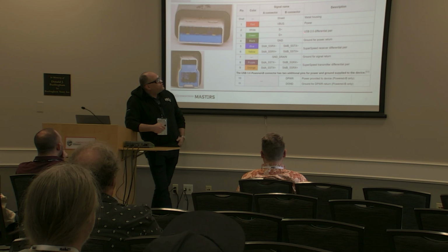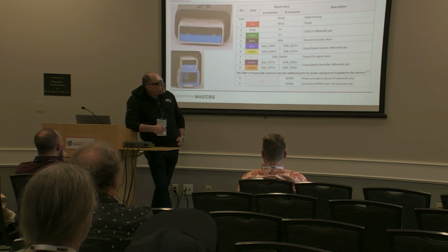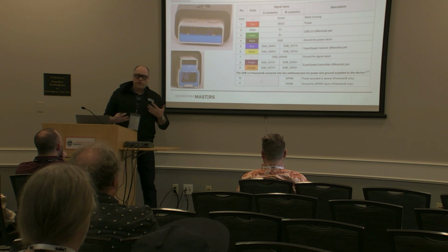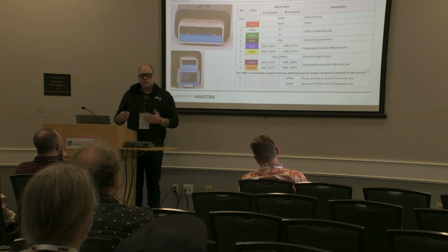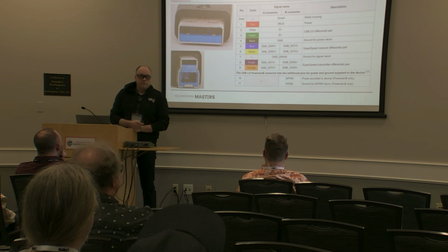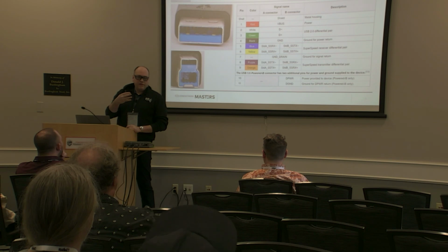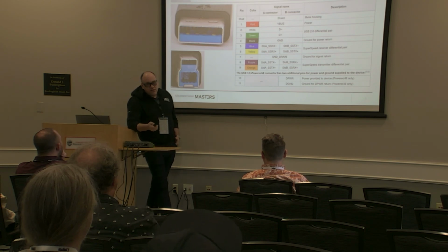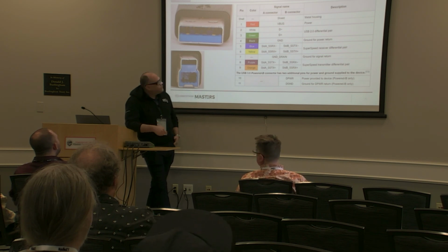So the point is this will carry the same 480 megabits on those 2 pins, but because we have these 2 extra differential high-speed paths, we are now able to get up to 10 gigabits depending on how you encode, right? What the device is actually doing to encode it. And we're not going to get into encoding. Question? Curious, does it use the 2.0 pair when you're doing full? It does. That's how it gets its first 480 megabits of data bandwidth. So anyway, that's actually the point I'm trying to make, so I'm glad you caught it. We are actually stacking, and that's how we're getting those pathways in. So